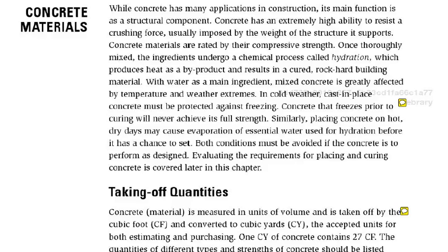In cold weather, you may add hot water. In warm weather, you may add ice to the concrete to keep it cool and to keep the temperature proper. So again, it's very important for the mechanical purposes of the concrete and the strength to protect it against weather extremes. One of the other things that you have to consider when you're working with concrete is that when weather conditions are real bad, it slows production down.